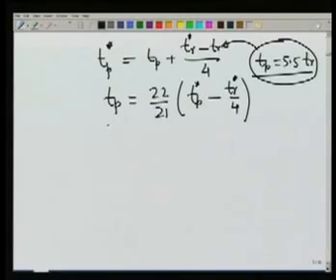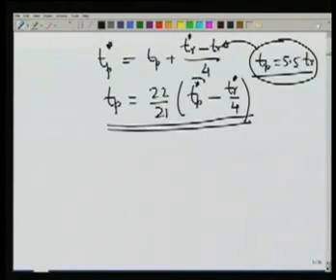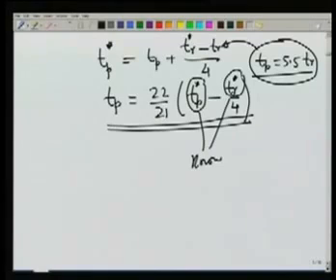So using this information, Tp star and TR star, these are known because the catchment is gauged, and therefore we have unit hydrograph for duration TR star, and we also have the time to peak in terms of Tp star.